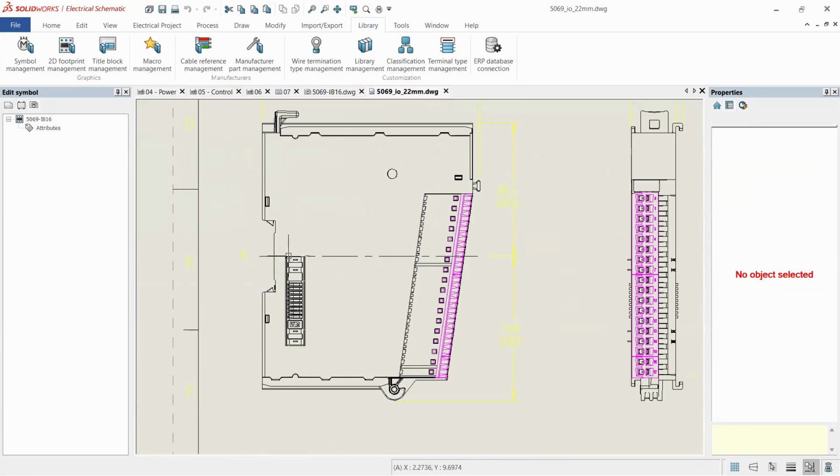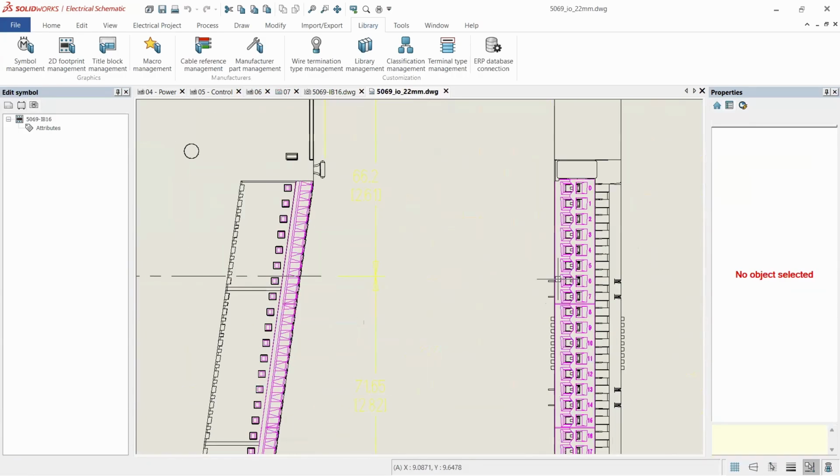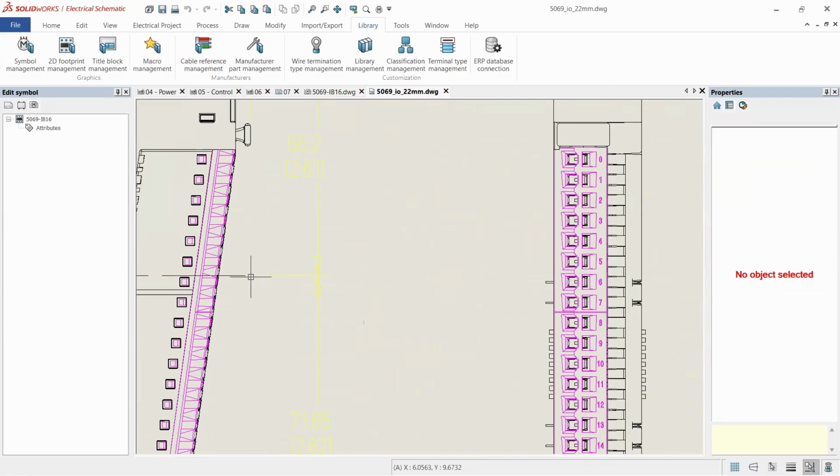When we insert them, if we put the insertion point in the middle somewhere, we could snap it on our cabinet layout to the center of the DIN rail. Comes in handy. If we leave it down here in the corner, we're just kind of guessing at where the middle is, right?